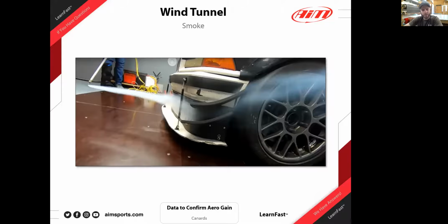Yeah. So the canards, a lot of people, if I'll throw a number out there. Every car is going to be different, I got to preface that. But this particular setup at 100 miles an hour made about 45 pounds of downforce on the front, which is pretty substantial, especially since the front of the car was around the 100-pound range. You can see the splitter is pretty small.